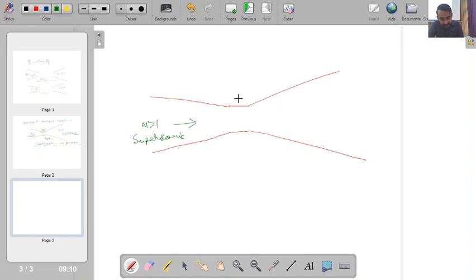Once again at the minimum area I will get Mach number equal to 1, a sonic situation, and after this, as my area increases, I will have a subsonic situation with decrease of Mach number.